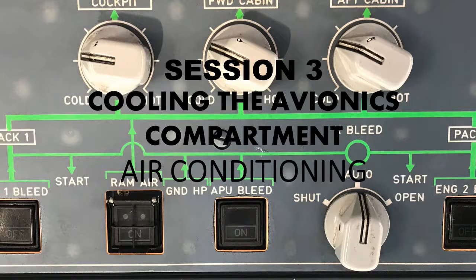Okay. There's also a conditioned air inlet valve that's actually installed in the main supply duct for the cockpit. Okay, so the cockpit supply air, this is different. I'm going to talk about the circuits in a bit, but one of the ways that you can cool the equipment is through the cockpit supply air into the system. And that only happens if there's a failure of the blower fan, the extract fan, or the computer itself. Or if smoke is detected, then that's when we're going to have the air coming from the cockpit supplying the cooling and ventilation for the equipment. Okay, so that's one way.